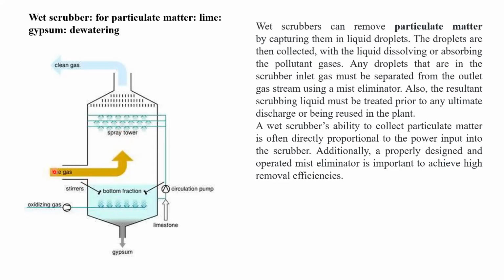While the flue gas flows in the upward direction, water is sprayed from the circulation pump, so that the droplets of ash and water fall down to the bottom due to their weight. The humid gas which is going to the atmosphere may still have many particles, and they are eliminated in the eliminators, just like drift eliminators in the cooling tower.